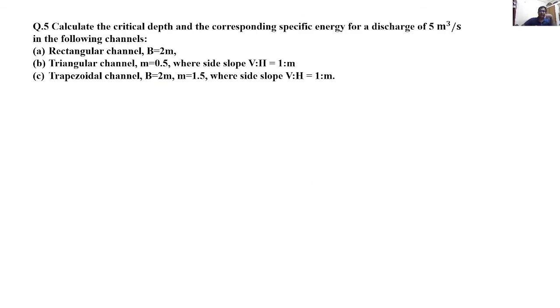Now we come back to the question which was originally posted in the discussion forum about the trapezoidal channel. However, I thought of solving it for a rectangular and a triangular channel also, just to give a brief idea about how the calculations are performed. So the question is, calculate the critical depth and corresponding specific energy for a discharge of 5 meter cube per second in the following channels.